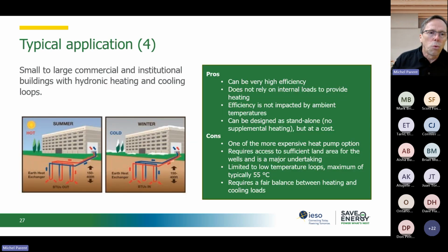So if you want to do a rough estimate, take your heating, translate it if it's in cubic meters of gas, translate that into kilowatt hours, obviously taking out the efficiency of the boiler. So take 80% of your cubic meters, put that in kilowatt hours, and then divide by 3. That will give you how many kilowatt hours you will need to run a ground source heat pump. The difference with the total kilowatt hours would be your savings.